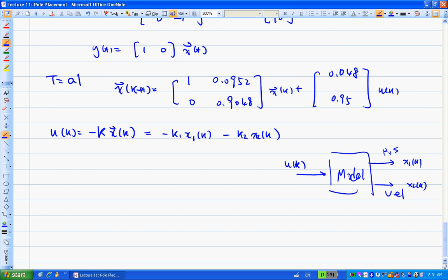So what are we designing? We're designing a pole placement controller. So what do we do? We basically insert a gain matrix here, the K. These two feedbacks you can usually combine into one block, one line over here. Then that's a simple pole placement controller.